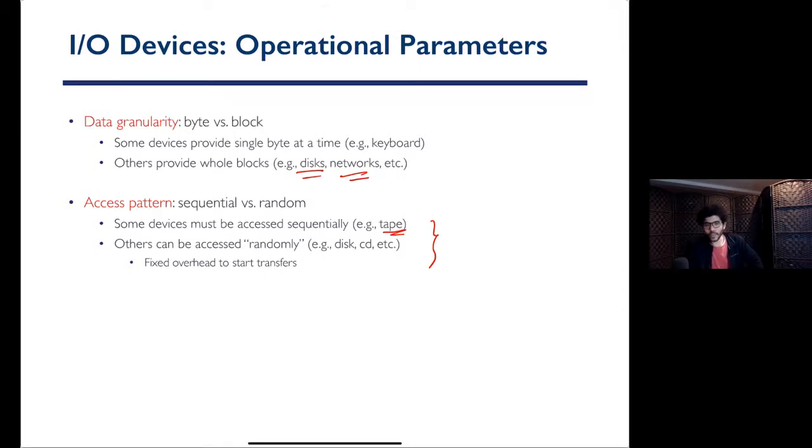It's important when you're designing your interface to know if only sequential accesses are permitted, or if random accesses are also permitted. Also, you might want to know if sequential accesses are faster than random accesses. Like if you have two accesses that are sequential, then the average time for each one of them might be much less than if the first access is here and then the second access is a jump to somewhere else. So these become important.